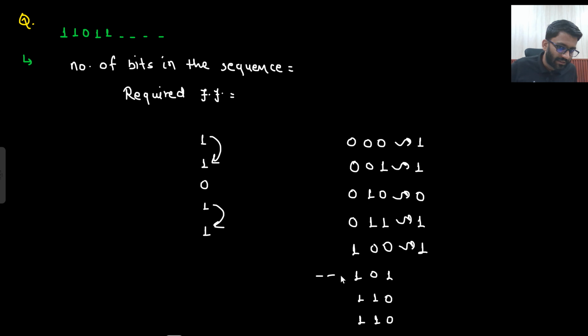If this state comes, what am I going to do? I am going to clear it. Say yes or no. Here I will clear it. This I don't want. So I want my output to go from 0 0 0, 0 0 1, 0 1 0, 0 1 1, 1 0 0. Just as I get 1 0 1, the output should be cleared. Are you getting this point?